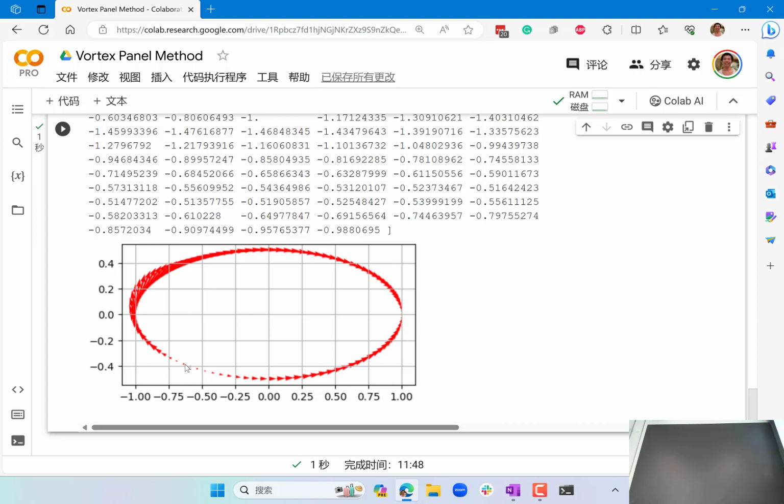So you're right. For this one, if you actually run the flow field calculation, the separation point is probably not going to be here. It's probably somewhere over here. And if it's a viscous calculation, there are probably 2 locations of separation, and there is a wake over here. So if you run a viscous calculation, the flow is going to be different from this. But if you have an airfoil geometry, we are going to be enforcing the Kutta condition at a known point on the trailing edge.